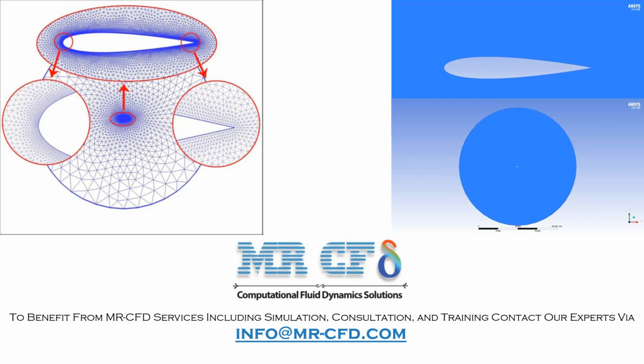To solve this problem, after defining the domain, an unstructured triangular mesh has been applied around the airfoil. For the boundary layer flow, finer meshing is applied near the airfoil and gradually gets bigger farther away, in order to make it easier to solve and reduce the computational time.